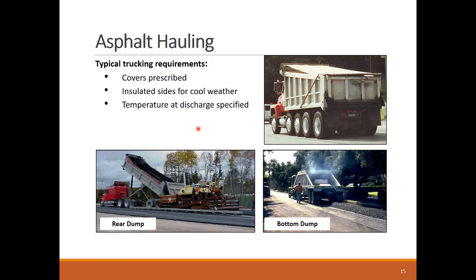The warm temperature of the hauled asphalt should be protected by having insulated truck box walls and cover sheets. The goal is to have the required warm temperature uniformly over the mix volume, otherwise the outer part of the asphalt will cool and segregate from the rest of the mix. The trucks can have two dump designs, depending on how the dumped asphalt will be handled.